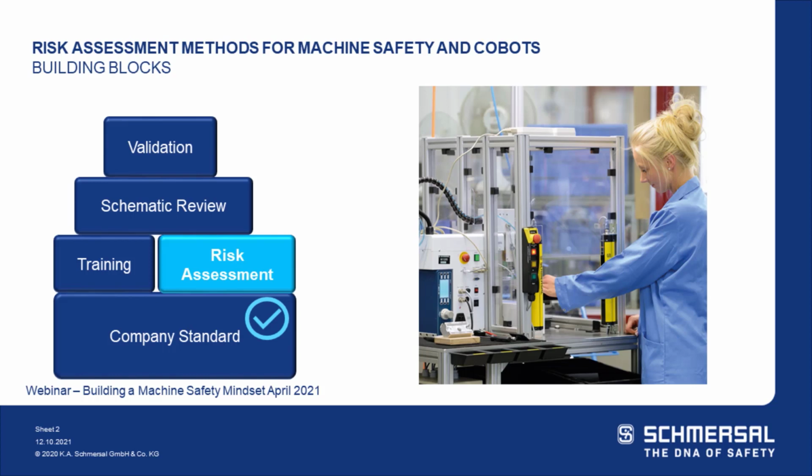I think we touched on this one, but is the machine builder required to do risk assessment when we purchase the machine? Yeah, that's a question. Here in our region, North America, it's not a requirement for the machine builders. Now, if you look at the robot standard, ANSI RIA 15.06, and I'm pretty sure this is the case, the standard really calls out that risk assessments must be done. If we look at Europe, it's the machine builder's responsibility to do a risk assessment, complete it, and provide a safe machine. But on our side of the pond, it's actually the end user's responsibility.